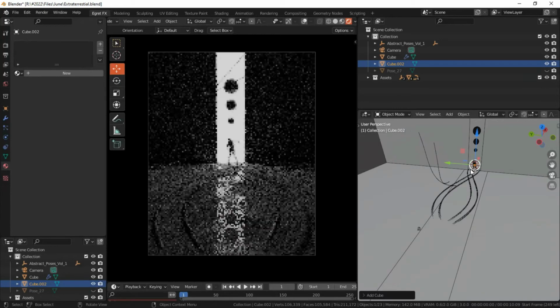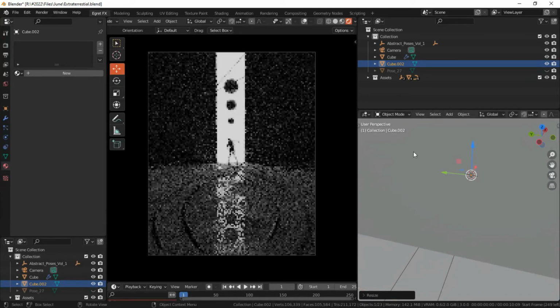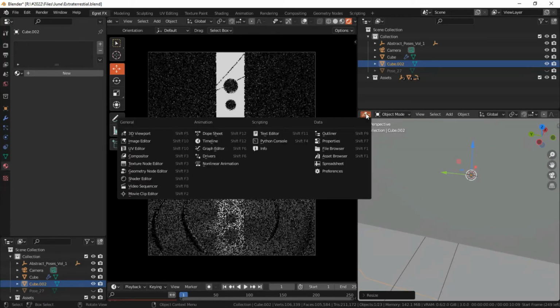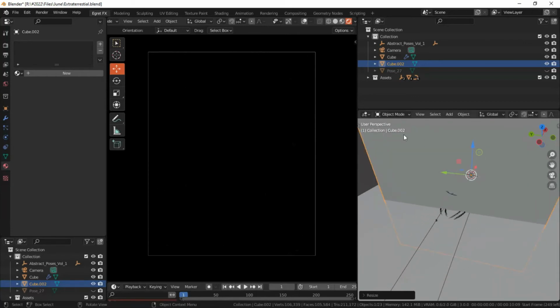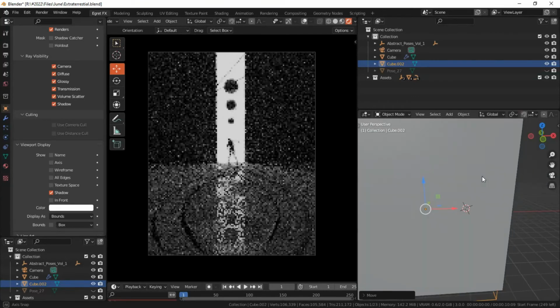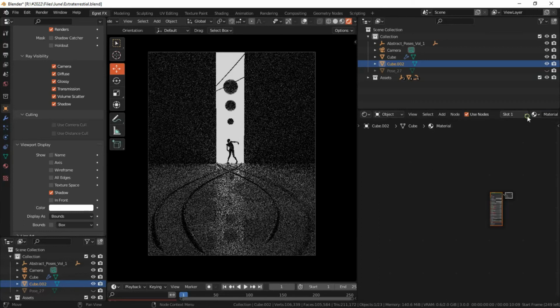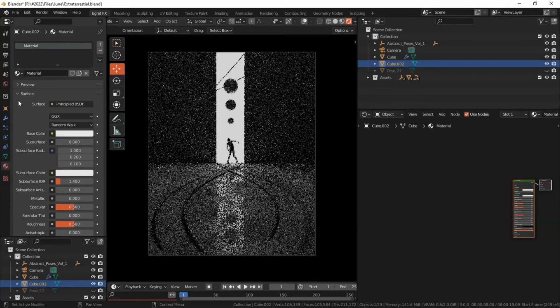At this point, it's also important to use volume to add ambience to our scene. I use a cube, and then I'm going to transform that cube into the volume object, and make sure that cube is encasing all your scene, so all your lighting should be inside the cube. I'm going to create a new material for that cube, and this is going to be a volume material, so make sure you use the principled volume shader instead of a principled BSDF shader.